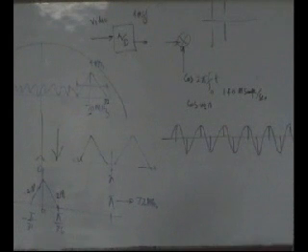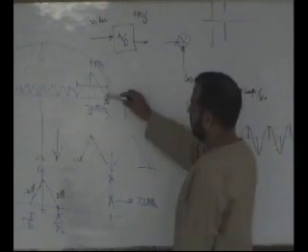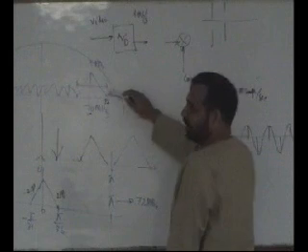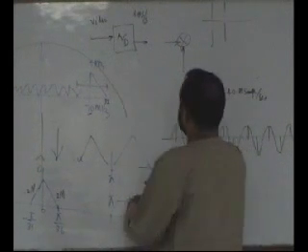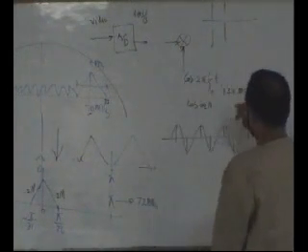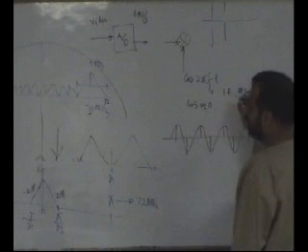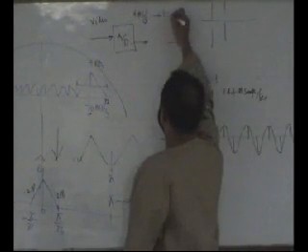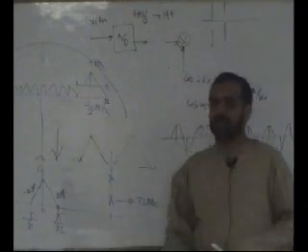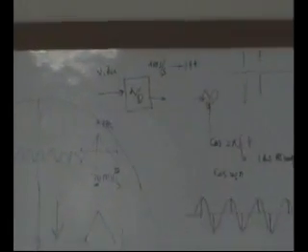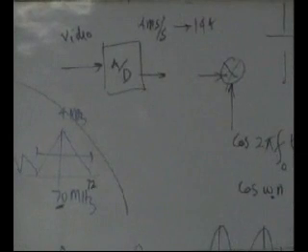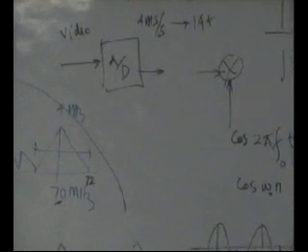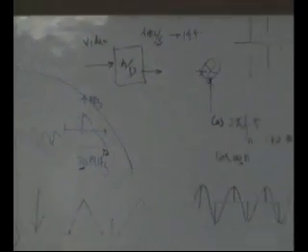Rather, you bring it up even more, because your highest frequency once you mix it is going to be 72. So that's the reason, instead of 140 mega samples, preferably make it 144 mega samples and bring it up to 144 mega samples. So you bring this signal up, and only then you can digitally mix. This is the only way you can digitally mix: you bring it up, and then you mix them together at the same sampling rate.